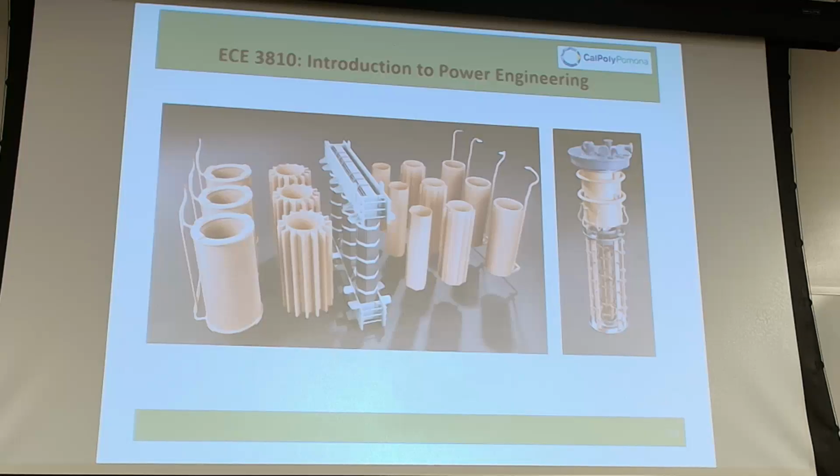So we were doing the testing, and that was the trick. It was about doing what they call impulse tests, where you apply very high voltage impulses on the insulators to see how the transformer will deal with lightning or high switching transients. And the transformer didn't pass. That's a big deal because the transformer needs to be delivered. If it's not delivered, you're not transforming energy, and if you're not transforming energy, you're not making money. There is a date where the transformer should be energized, and it must be right on that day.